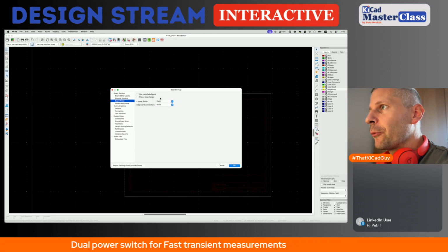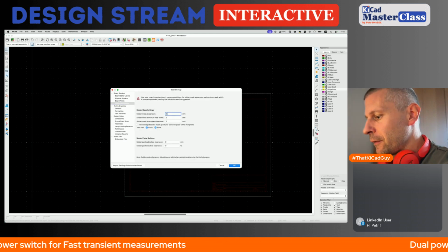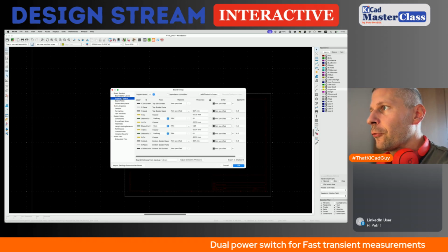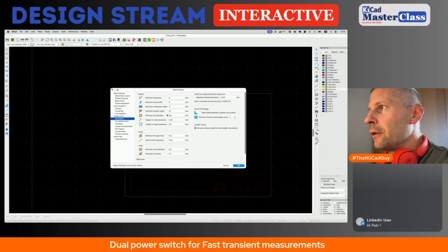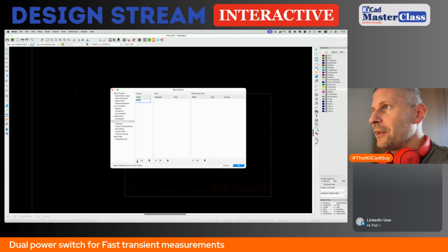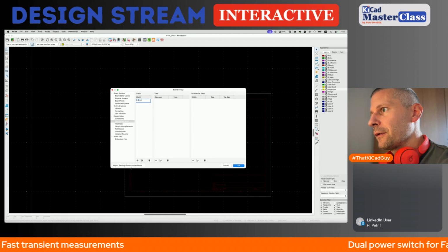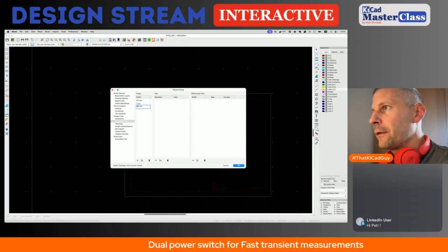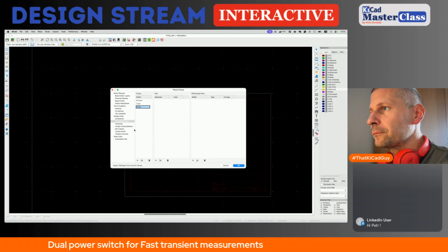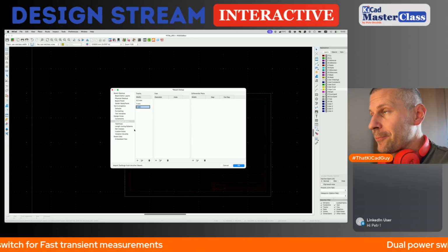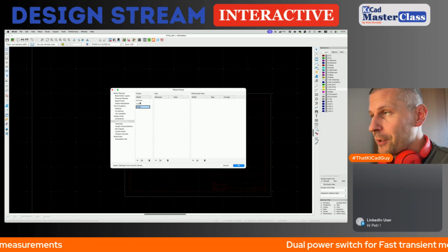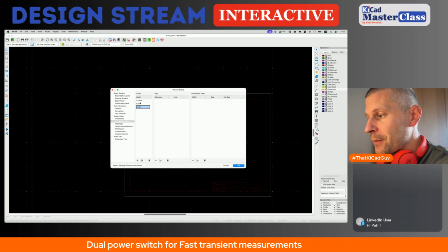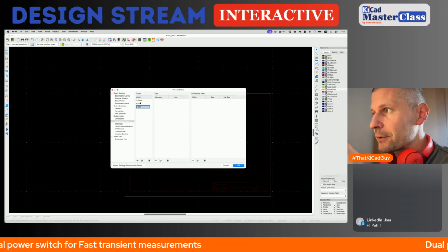Board finish, not important, but just for renders. Yeah, 4 layers, definitely. Constraints I can keep, and the predefined, I think, will be as usual. Plus, yeah, probably I will use only 0.5 millimeter or 1 millimeter track width, and larger track width will be used as polygons.